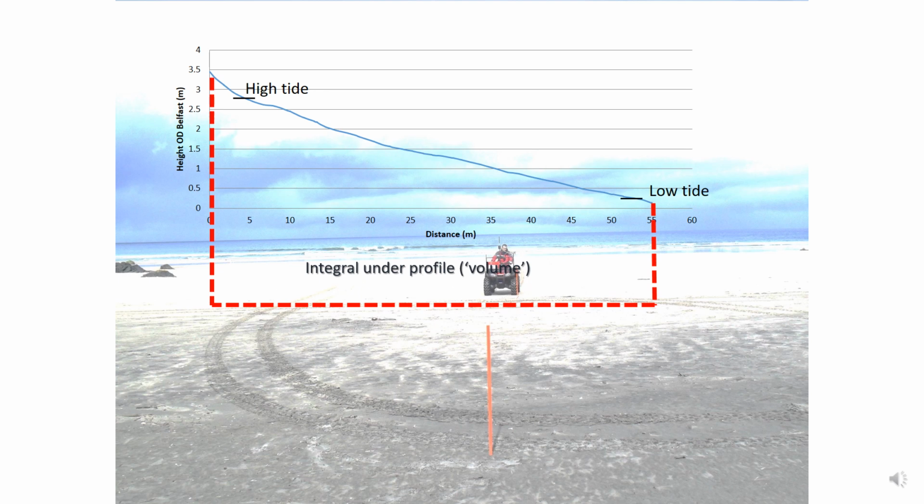So effectively what we do is take an integral of underneath the beach, and we calculate the area under each profile, and we use that figure as a way of quantifying the volumes of the beach at any one particular month.